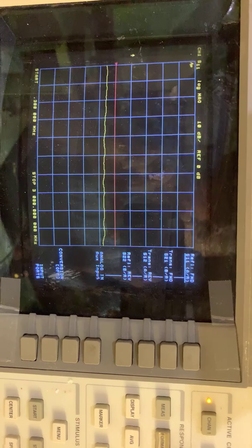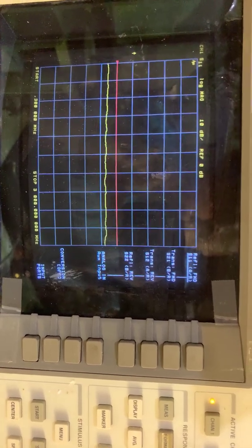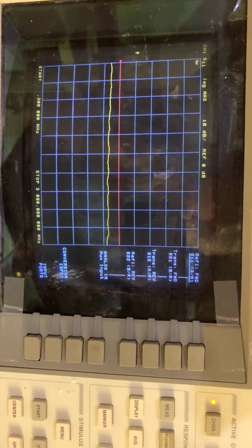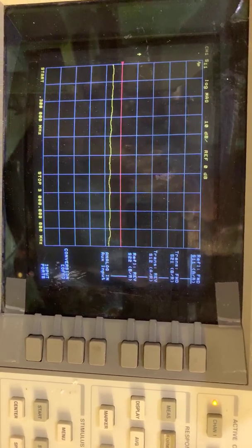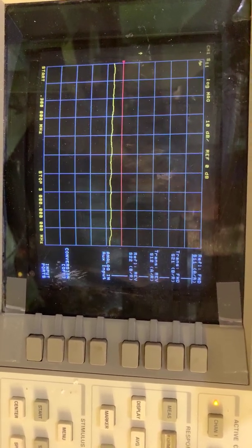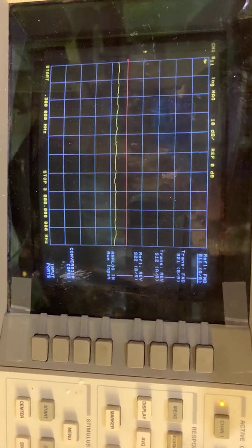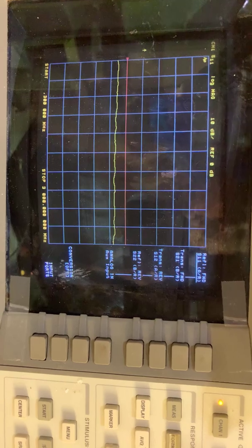And if you do RF design, you come across S parameter files for your active devices that are used in simulators or even in a Smith chart to design matching networks. Vector network analyzers can measure S parameters.